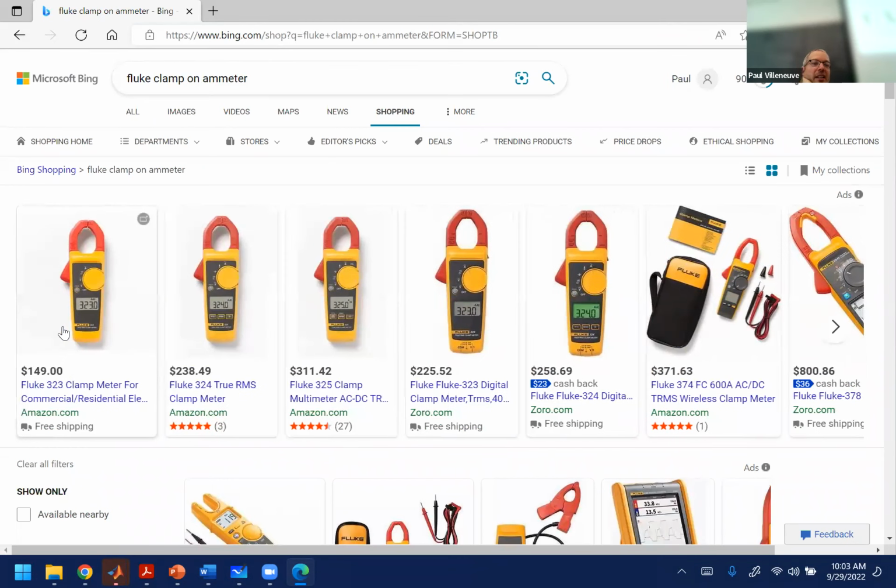Now somebody's gonna say, hey, Paul, you're BSing me. What if this only goes down to a range of 200? You can only measure 200 amps. How can you get more accurate? You take your wire and wrap it around inside your clamp a couple of times if you can. And each wrap multiplies. So when you have 2 wraps in there, it doubles the current. 3 triples, 4, 5, 6.